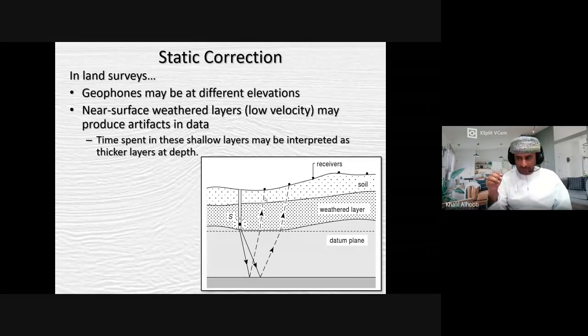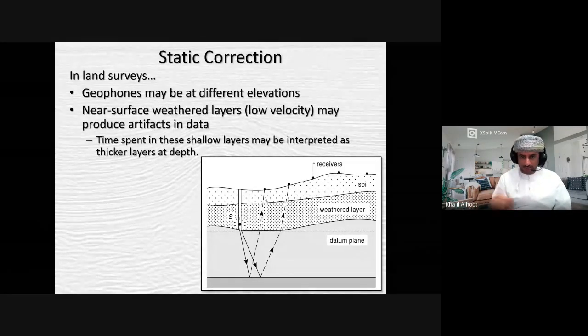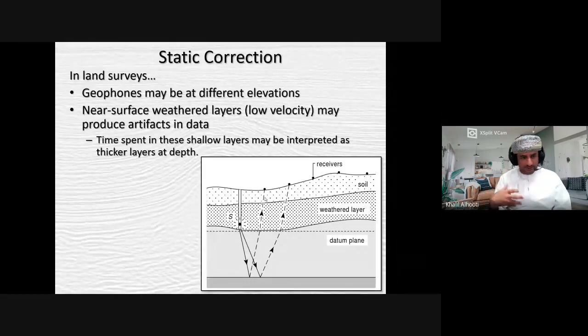The people who are drilling get the samples coming up. The drill bits bring the samples, or cuttings, to the surface, and you can touch them. You can get an idea what type of rock it is. Is it a hard rock? Is it a soil? And it gives you a control point, at least, of exactly where the depth is. You can combine both of them probably.